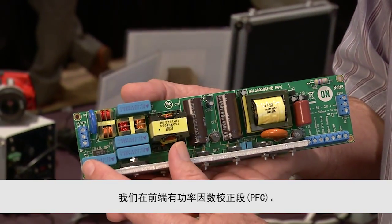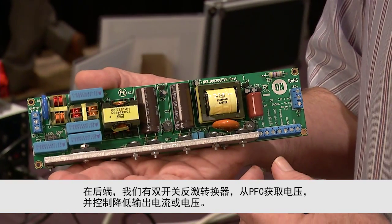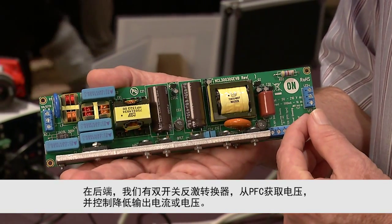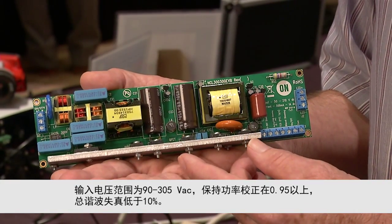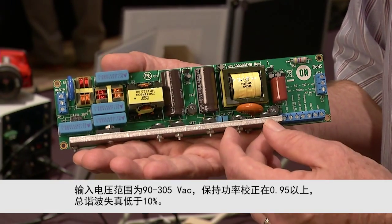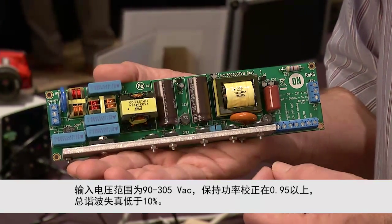We have the power factor corrector stage in the front end, and then on the back end we have a two-switch flyback converter that takes the voltage from the PFC and controls it down to either the current or the voltage controlled for the output. It has an input range of 90 to 305 volts AC, and it maintains power factor above 0.95 with a THD much below 10%.